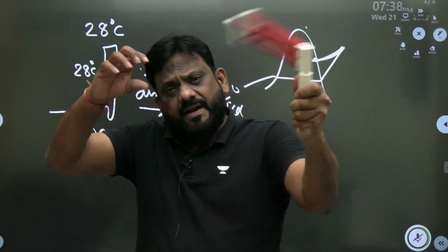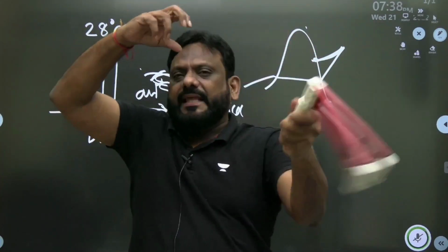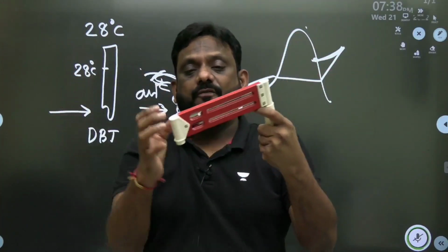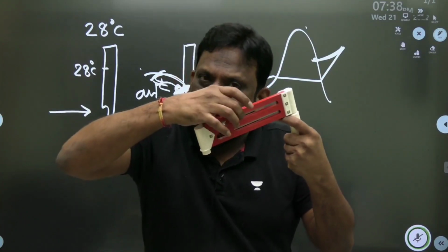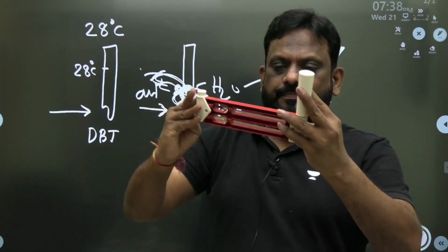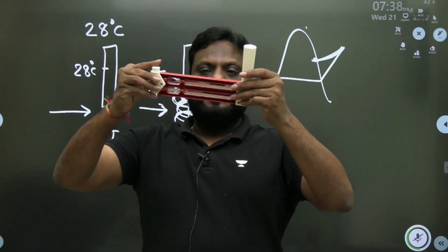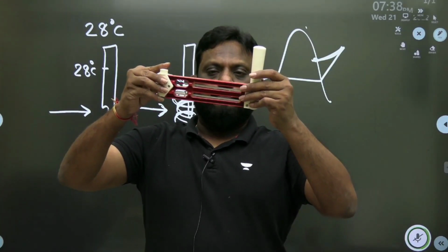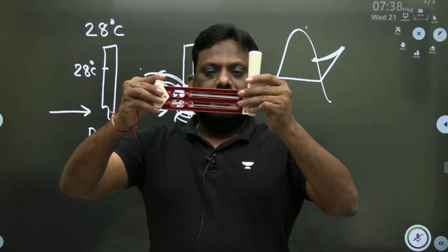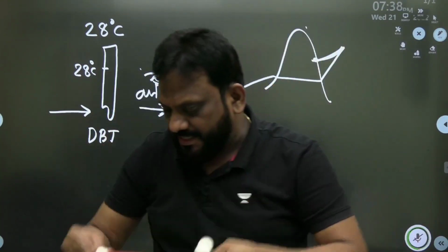The wick which is covered with water, completely saturated with water, the air absorbs that moisture, and thereby in the process of evaporation, observe here, the temperature of this wet cloth, the thermometer covered with wet cloth, will come down. Now let me tell you, oh my God. So AC is running here, so now the dry bulb temperature is about 24, and the wet bulb is around 19 degrees centigrade. You cannot see it, it is 19 degrees centigrade.